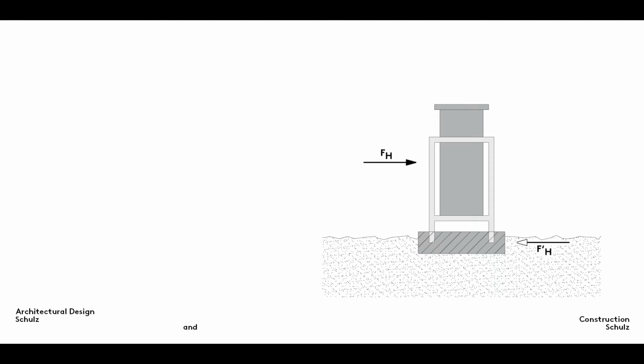But what happens if the wind blows when no one is pushing against it? The counterpressure acts below ground, where the litter bin is securely fixed in the sand. Here, however, the action and reaction forces are not operating on the same line of action, but at an offset. What does that mean? This offset in the force couple produces a lever arm. You may remember this equation from your physics lessons. Force times lever arm equals torque.